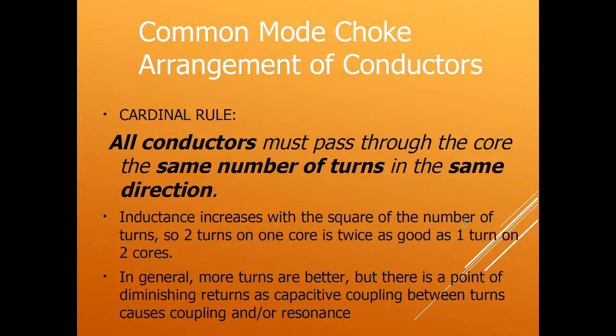And so trying to get more turns on it is useful and it's often better, but there is a point of diminishing return. So there is capacitance between the turns, and if you get too many turns on there, you'll end up having so much capacitive coupling through it that you're defeating the purpose of having the inductance part of it. And that kind of gets beyond the intro level.